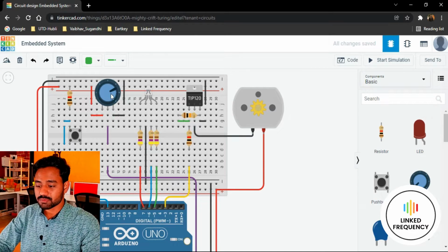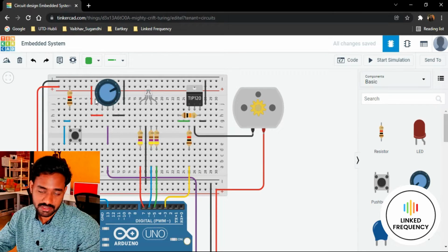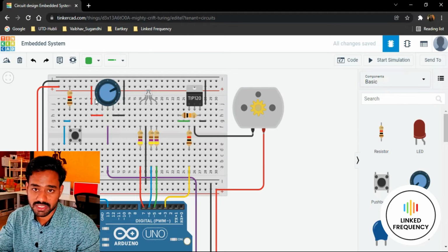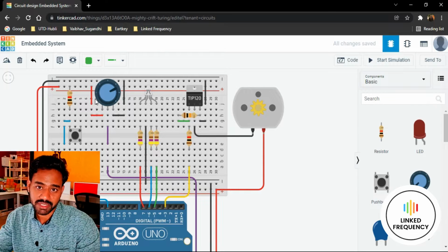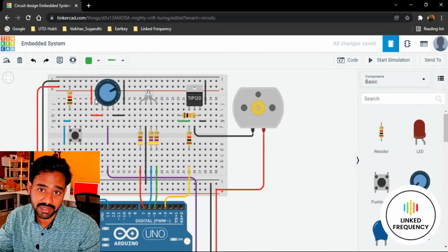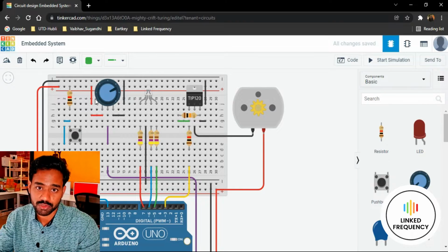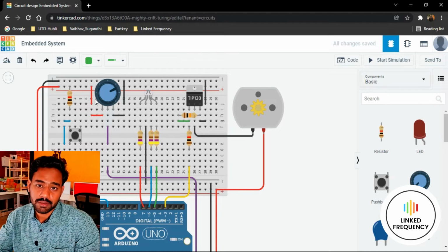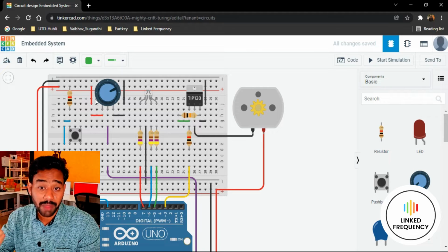First of all, this potentiometer ranges from 0 to 100. I remapped it. It is originally 0 to 1023, because we are using a 5 volt reference here, and when 5 volt and 0 volt are referred, the 10-bit SAR ADC inside the Arduino development board converts that value from 0 to 1023. However, I'm using a new function, the map function.